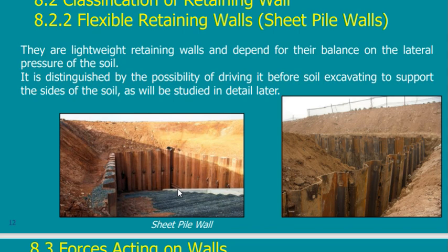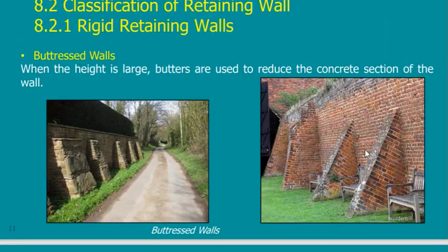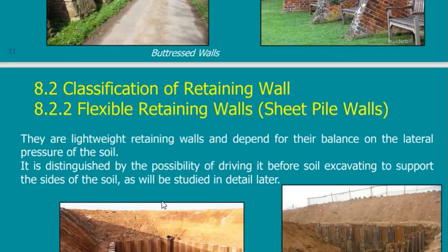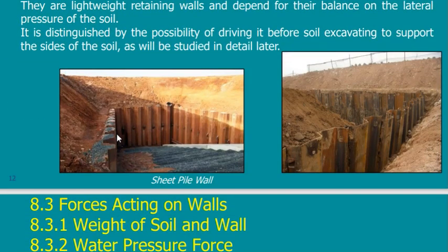I don't need it anymore because I only need it to construct some footings below and then backfill again. So I don't need it for the time span. So in this case, I'm not going to construct all of these huge constructions. They need space, time, and money. So in this case, I will do something temporary. Usually we call it a shoring system or a side support system.